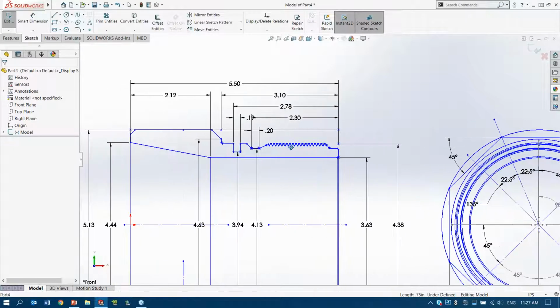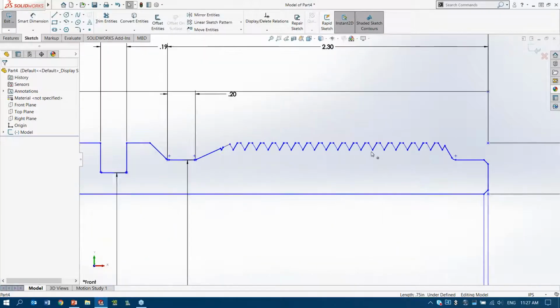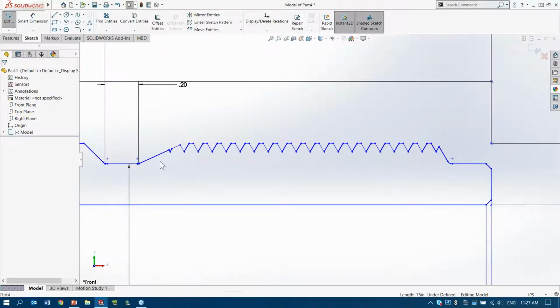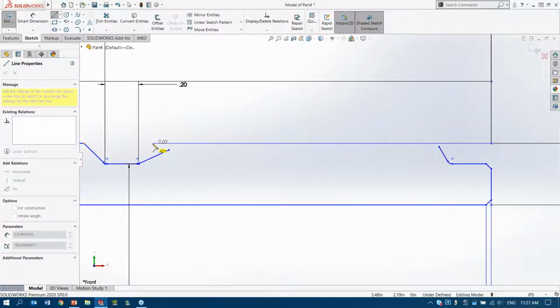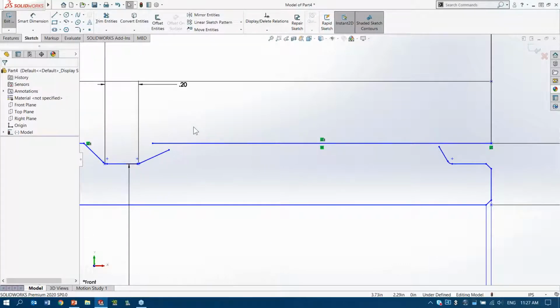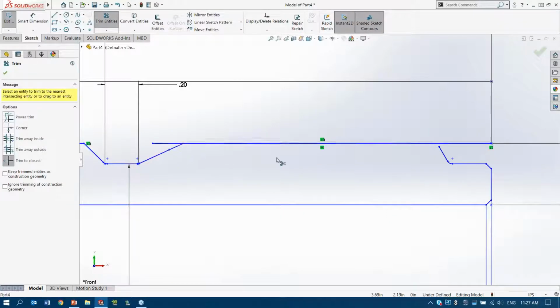And one thing I want to do here is recreate that model, but I see that the fillets on top here need to be taken care of. So if I just do a revolve, it won't be a functional thread. So what I'll do here is remodel this a little bit. Use the L key on the keyboard to draw a line, just like AutoCAD, by the way. I'm going to use my trim extend tool. It works very similar to AutoCAD, so I can extend and trim in the same tool.